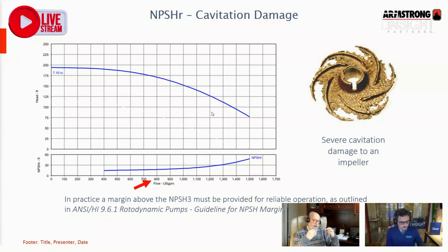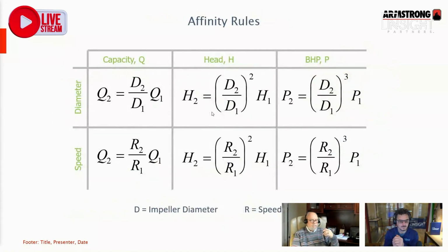So the other thing to consider, and test and balance guys typically will use a differential pressure meter. There's a whole bunch of them out there on the market. TSI makes one, Air Data makes one, Alner makes one. There's a bunch of different ones out there. Hydrobalance makes one. And it has two hoses on it. You put a hose on each side of the pump for high and low, and it'll read the actual differential across the pump. If your design firm doesn't have one, I really suggest you get one. They are invaluable in going out and troubleshooting what your pumping system is doing and how it's behaving and how it's operating. Gotcha. Thank you, Tony.